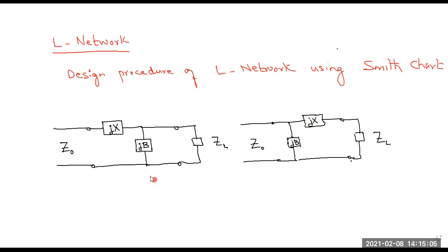During our last lecture, we outlined that whenever you design an L network, you have to take two steps. The first step is to select the proper L network for the given load. Only one out of these circuits will be useful for us.